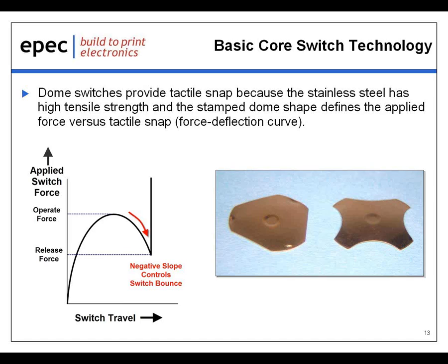The photograph shows two common types of dome switches where the diameter of the switch and the free height are some of the factors that determine operate force, snap, travel, and operating life.